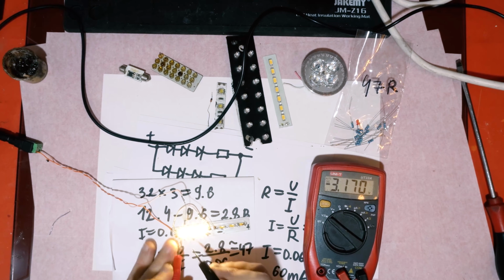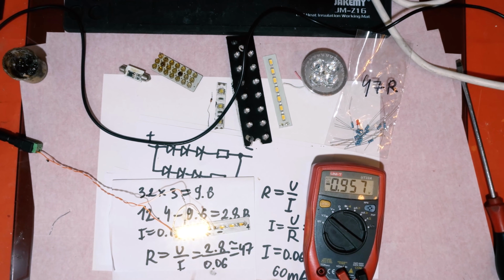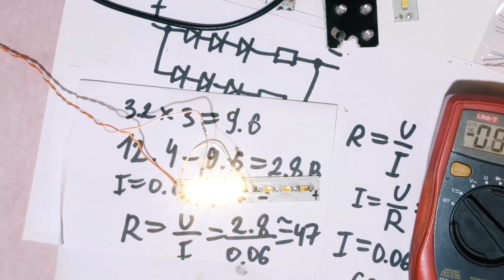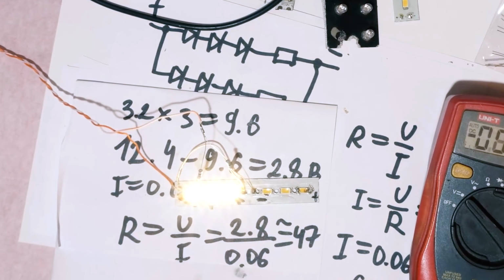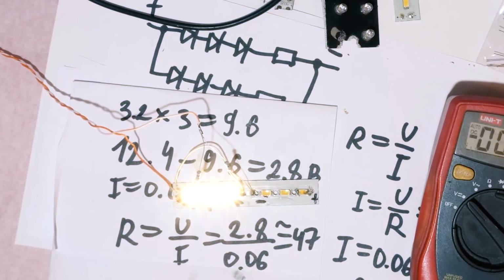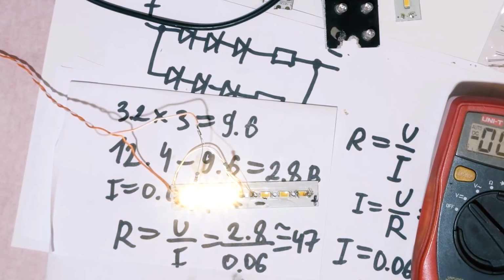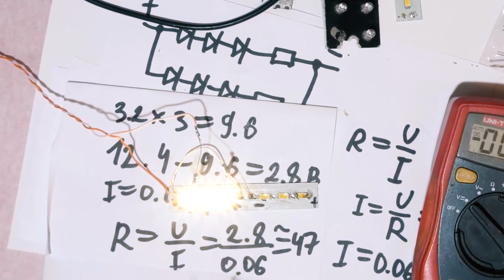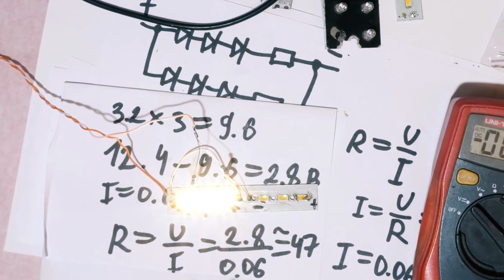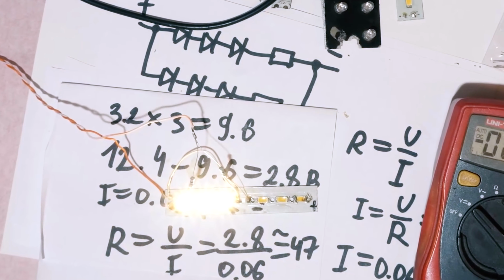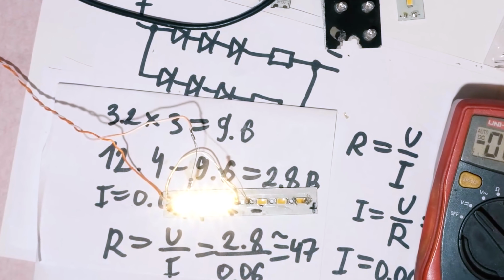One more thing to consider when using resistors to lower LED current. You have to realize that voltage drop across a resistor will cause it to heat up. This means you have to place resistors so that they do not touch anything, especially plastic parts or any parts that can, God forbid, catch fire.